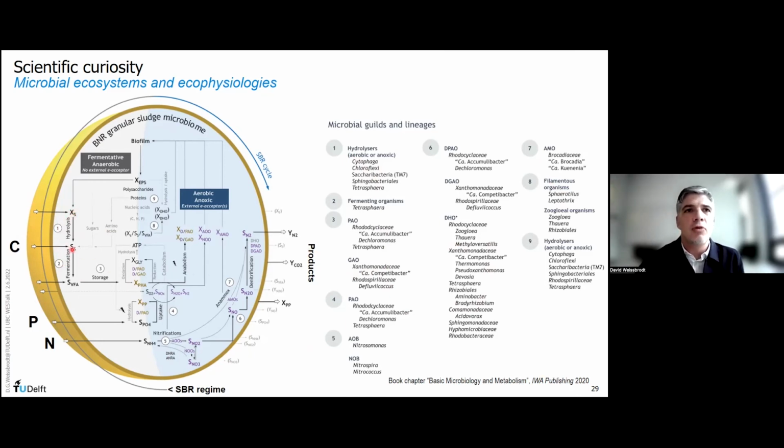So these are the pathways for carbon storage and removal, for phosphate removal, and nitrogen removal under anaerobic and aerobic conditions. Then we can also think about how these EPS are produced. And actually, within all these sets of microorganisms detected with sequencing, which ones are producing this EPS? Which are the good organisms to select to produce this EPS?